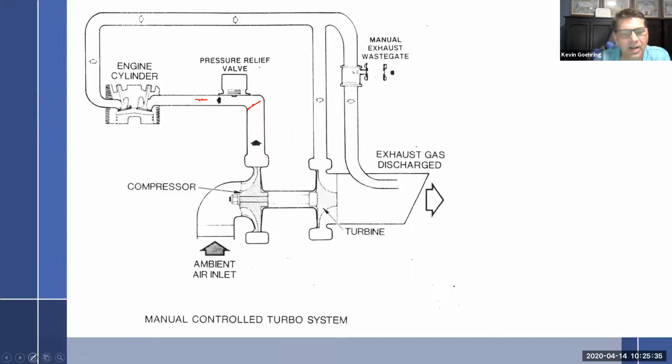That way you're actually controlling the upper deck pressure and what the compressor is doing, so you don't have too much pressure here. And then the throttle then controls manifold. So it works that way. So air goes through here, it gets to the Y. So here's my Y. And remember, Y is just a passage one way or the other.